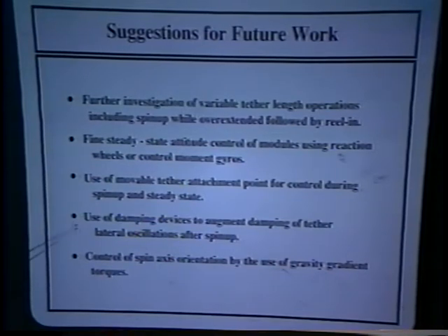The use of damping devices to augment the damping of the tether so that the disturbance torque exerted on the modules drops faster is an important area that should be looked at. Eric Stoneking is working on this research right now using my computer simulation. And the control of the spin axis orientation of the centrifuge is something that I didn't mention, but it is an issue of some importance, and could be accomplished through the use of gravity gradient torques on the spacecraft.